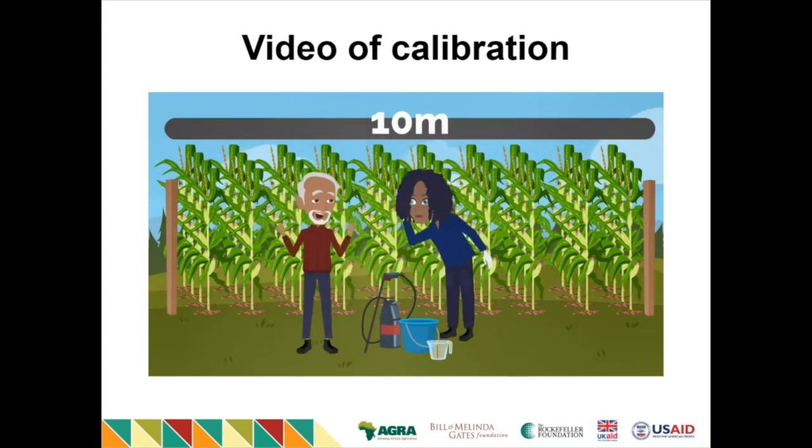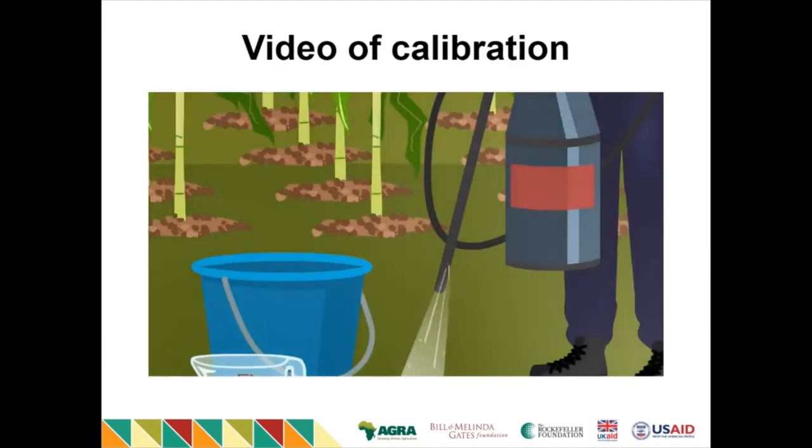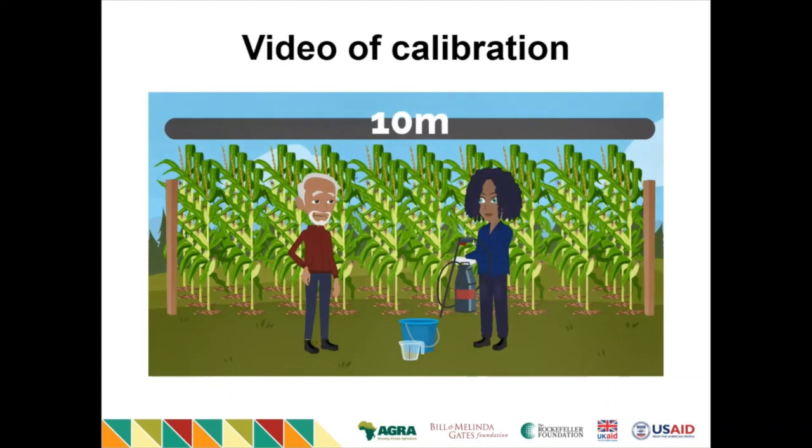This is where the bucket comes in. You'll have to spray next to the bucket first. Make sure you pressurize the spray as you normally would when spraying the fields. Spray into the bucket now and I'll start the 30-second timing immediately. When 30 seconds is up, you must move the nozzle away from the bucket.